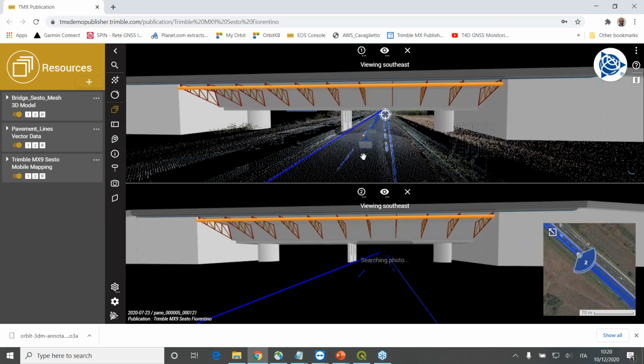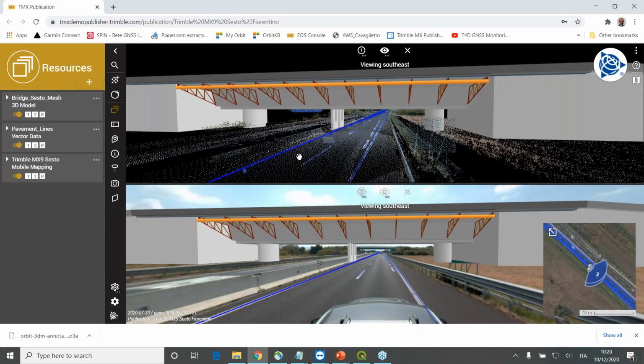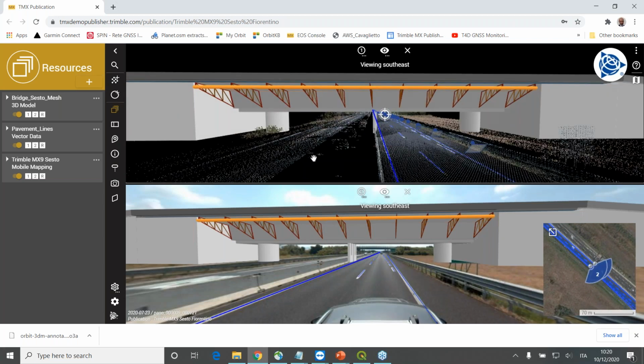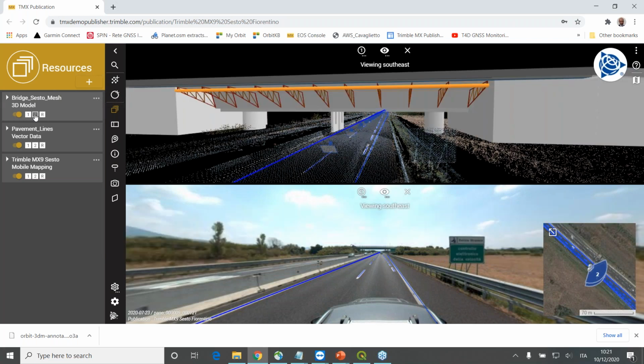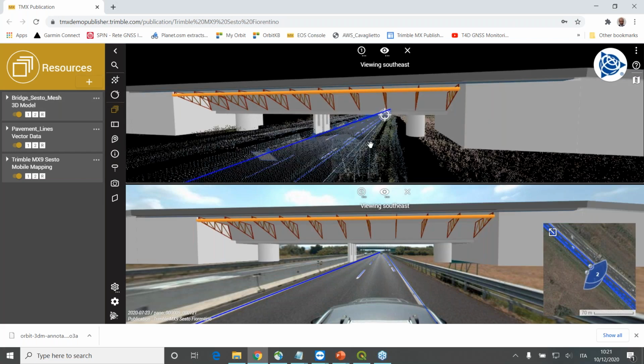So in a slightly different position than the annotation I created. You see, this is georeferenced, so this is fitting much better than the annotation which I just uploaded. And making use of these small 1 and 2 boxes, actually you can decide if maybe you would like to display just on top of the imageries. In that case, I can switch off the view from the view number 1. I click on 1. Otherwise, you can enable or disable the overlay from the spherical imageries. But let's keep it like this, for example.